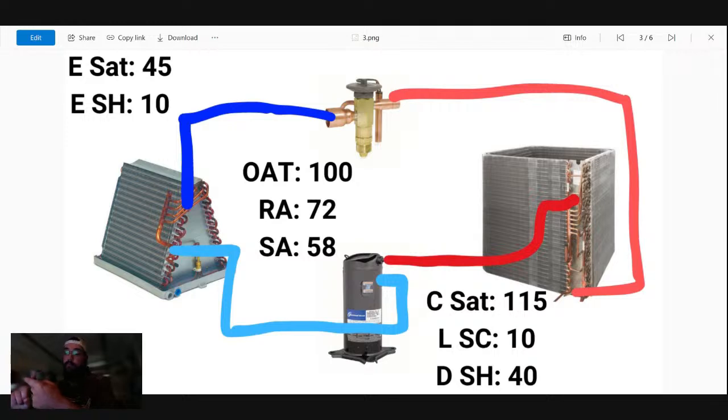What's my oil level doing? How clean is the coil? And if you're not confident, go ahead and clean it. Even if you just do that top section, clean the coil, and make sure all your condenser fans are spinning and functioning and spinning the right way. You'd be surprised how many fans I've seen run in the wrong direction over the years.